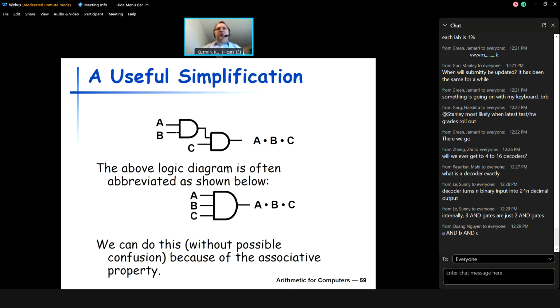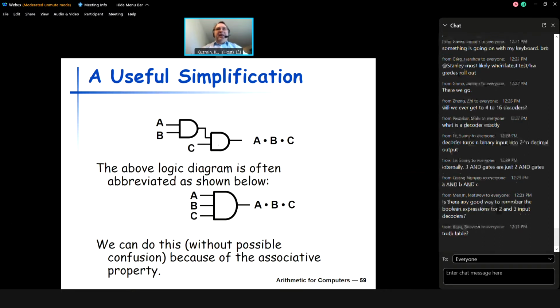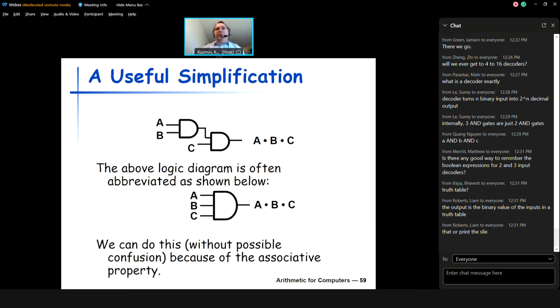So if at time 0 you supply A and B, then maybe the output will get the correct output value in, let's say, 10 nanoseconds. Okay, it's a small amount of time, but it's still not 0. And so if you cascade your gates, like in this example, you can see that their latency will be summed. Okay, the latency will be accumulated, because there's a latency that the first gate introduces, and then the second gate, since it is connected in series, in a chained manner, will add its own latency. So the actual output will appear after 2 gate latencies, not just 1. Okay, and that is important when we will be talking about the latencies and overall synchronization of digital circuits.